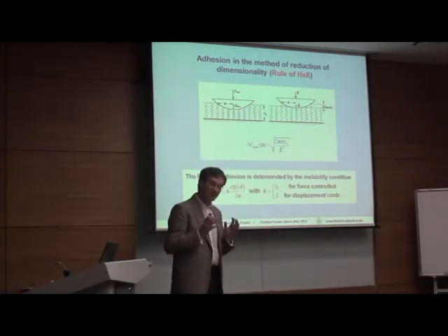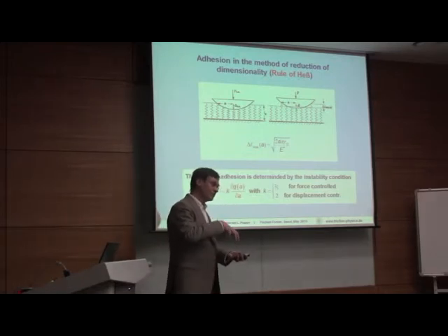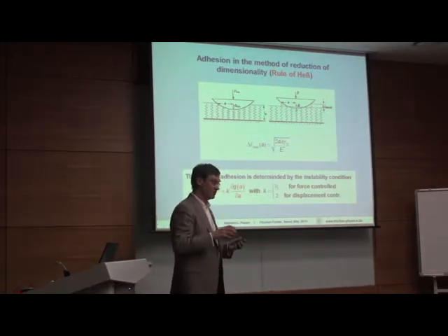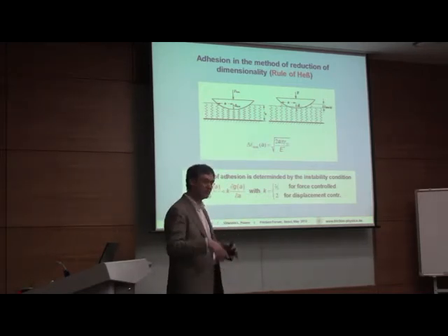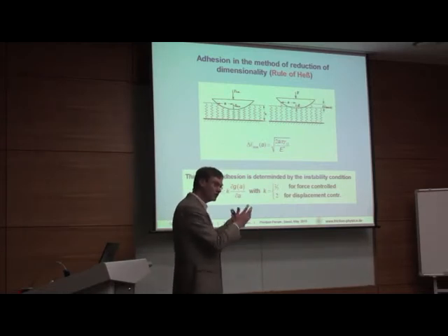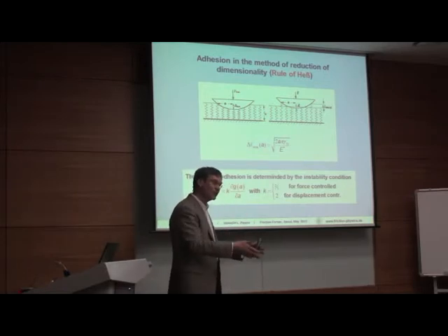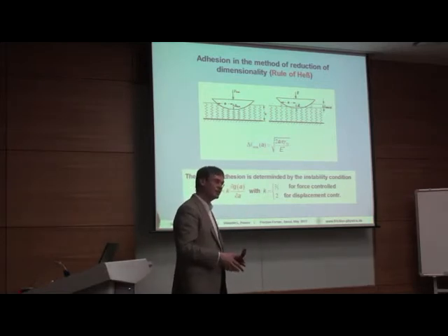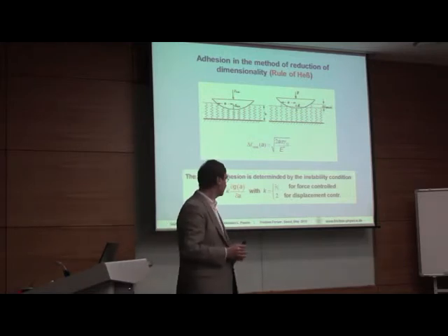And the statement is again, if you apply this rule, then the complete force displacement relation in 3 dimensions with adhesion will be exactly the same as in real 3-dimensional. For example, if you take the ball, then you will get the Johnson-Kendall-Roberts theorem, completely exact. If you take a cylinder, you get the exact cylindrical solution. If you take a cone, you get the exact 3-dimensional cone solution.